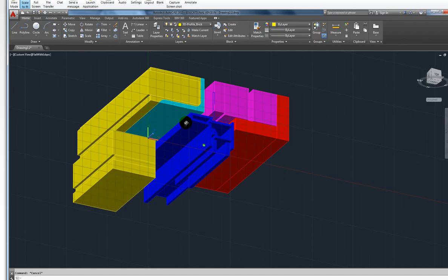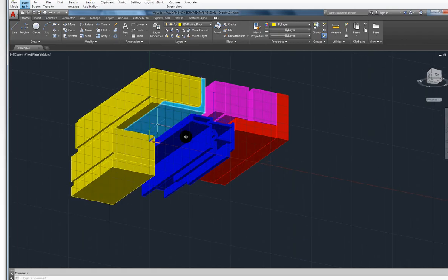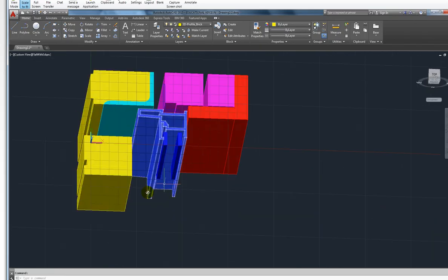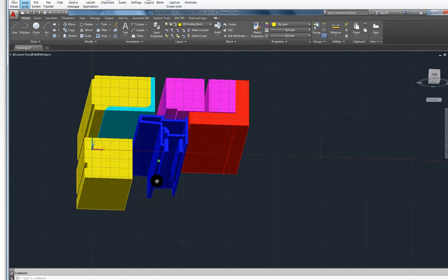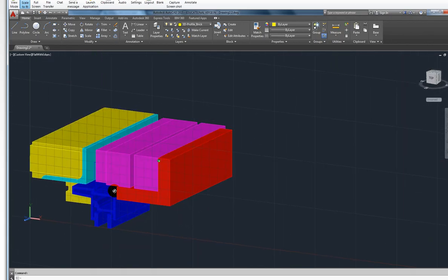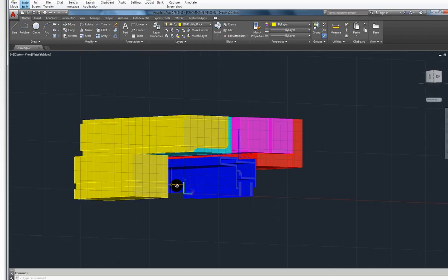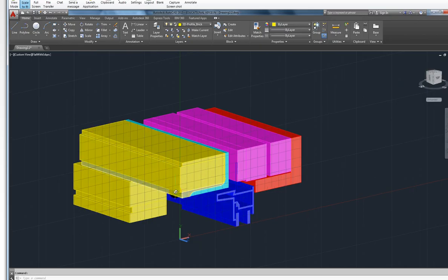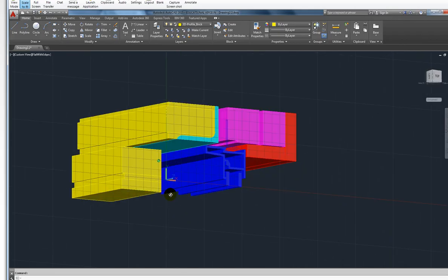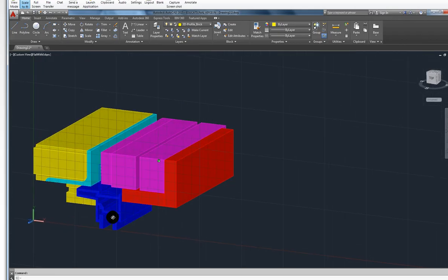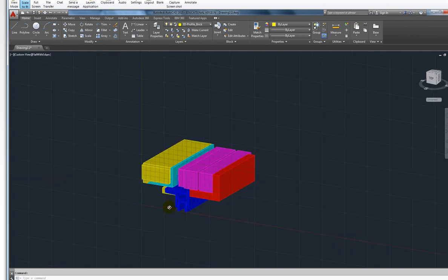So now when I look at this, I understand here's my mullion. Now this isn't right either, because this would turn down at that point. But that's fine, just get this going. We'll look at more complexity, because the window here in actuality would turn down wherever this brick is turning down, right? Does that make sense to you guys? We're sort of faking it right now. I just want you guys to get basic extrusion commands down.